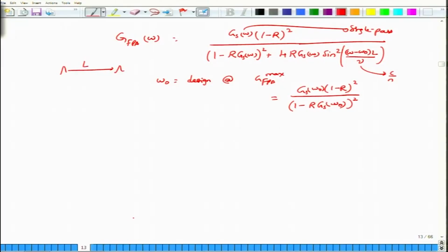That is the gain that the optical medium will undergo when it passes through the semiconductor optical amplifier of length L. If you now look at different values of R, you will get different values of gain. You can easily observe from this equation that the gain can actually go all the way to infinity.